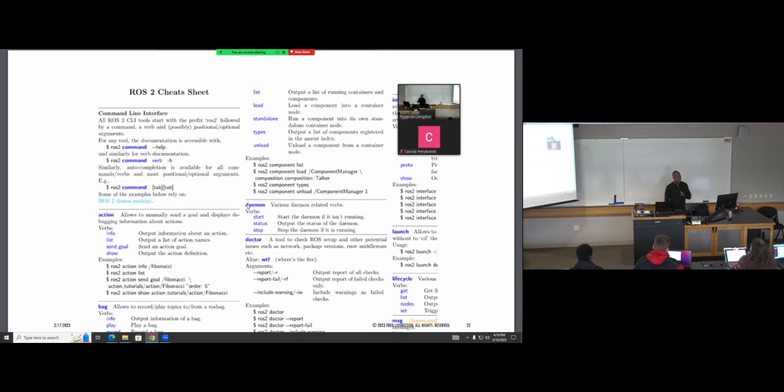But in a situation like that, it's always good, even if it's not running, to just have the laser scan and move the robot around the track and do a ROS bag record, and therefore you could have that data and then just play it back. You could go back home and actually work on your replay. So I do that a lot as well.